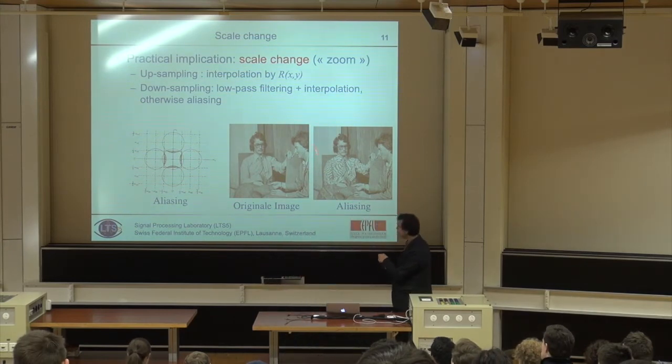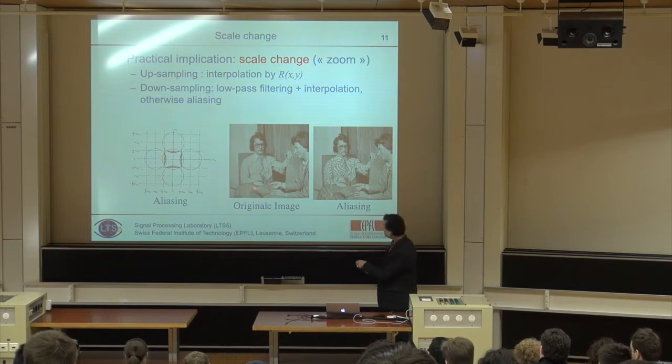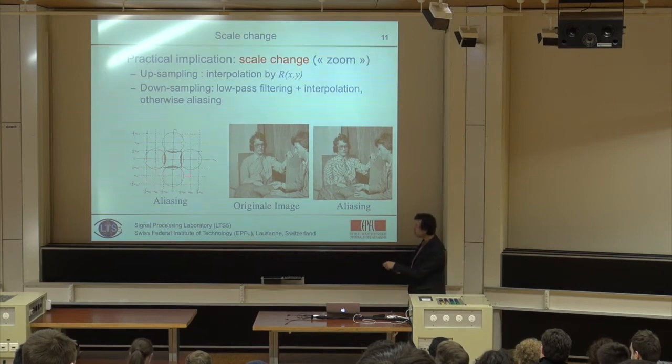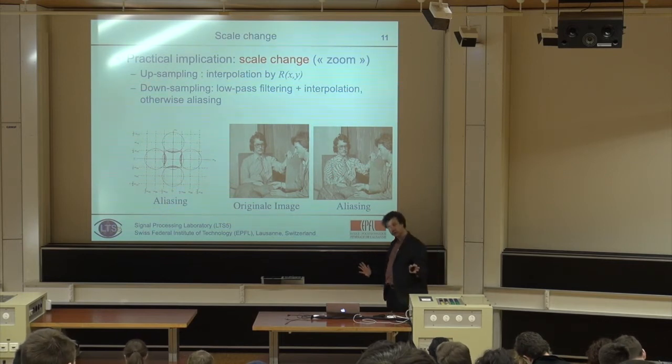And so from that, the high frequencies of the spectrum will basically be flipped back to the low frequencies, and those stripes which are high frequencies will be flipped back in the spectrum of your image, making weird things like lower frequency stripes here. This is typical aliasing.